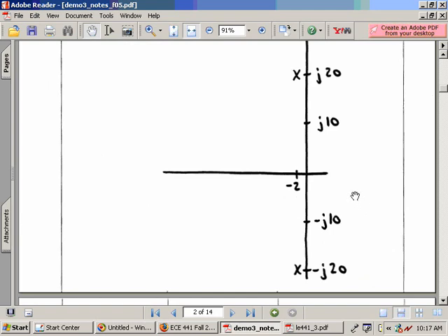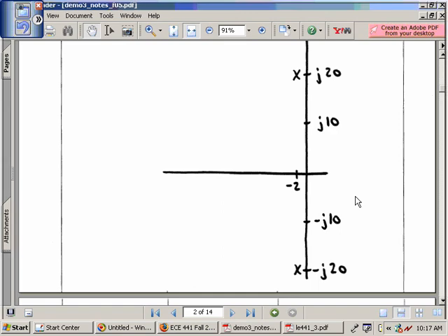We simply have 2 poles, and the root locus for this particular system, if we just had a gain, would go up and down at 90 degrees, and the closed loop behavior would simply be indicated by or determined by the amount of gain that we've introduced in the system, and that might then just make our system a little more oscillatory, but it's not going to change the damping at all. And so our overshoot is actually going to be deteriorated if we increase the gain K in that system.